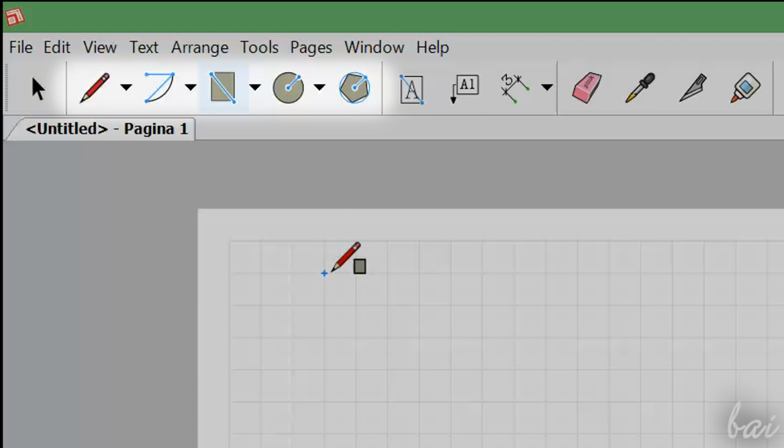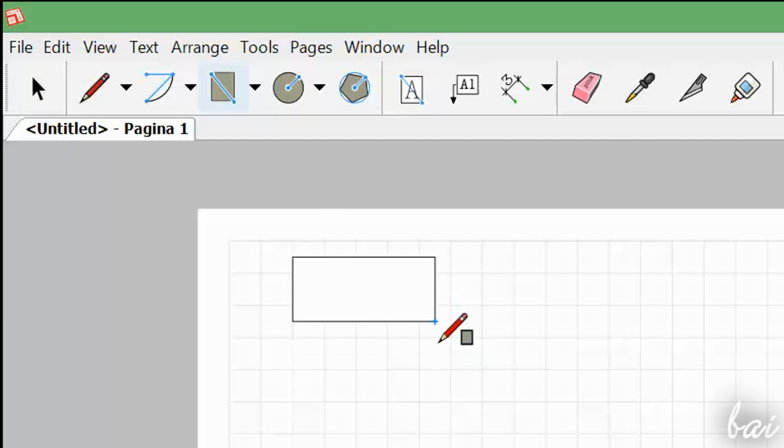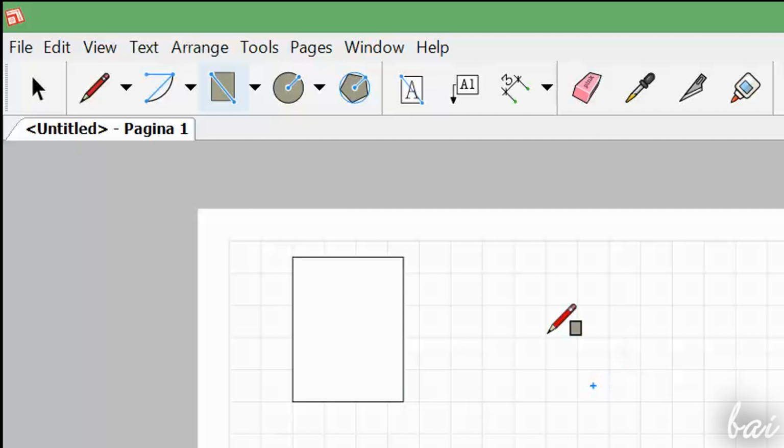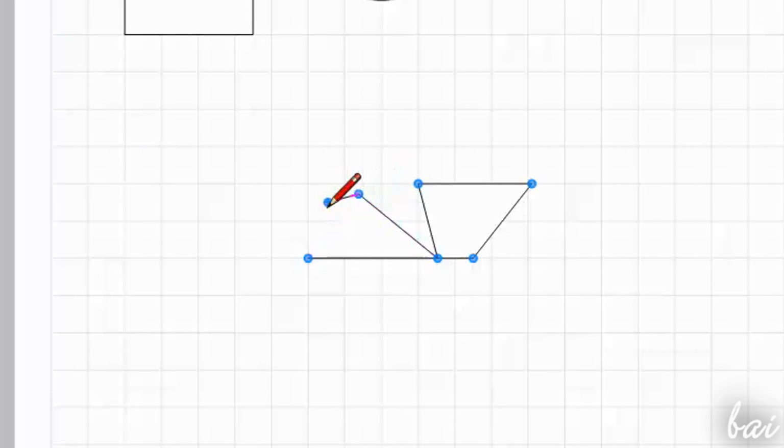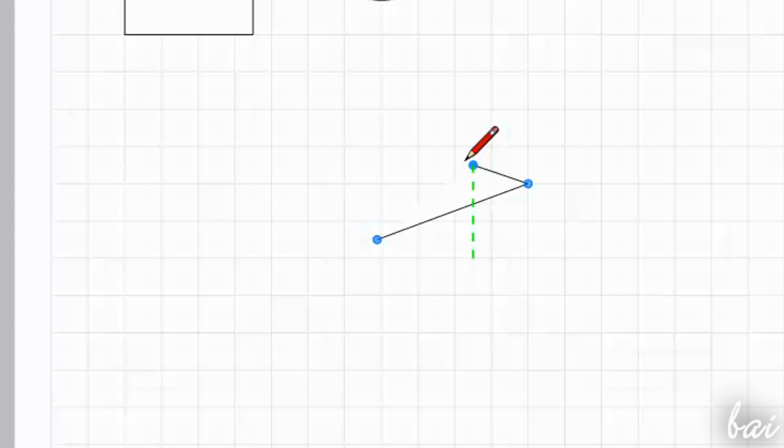The first tools on top are used to draw lines, rectangles, circles and polygons in the same way seen for the main SketchUp software. LayOut itself helps you while drawing, indicating each point or vertex through small blue circles, dashed guidelines to indicate parallel directions to the main X and Y axes and easy snappings to other nodes or objects' paths.